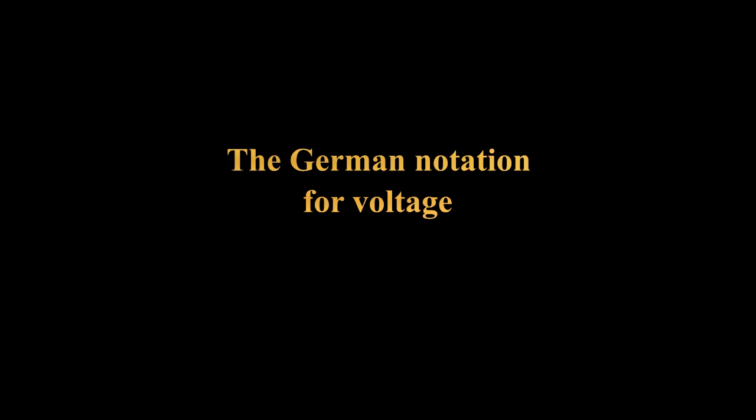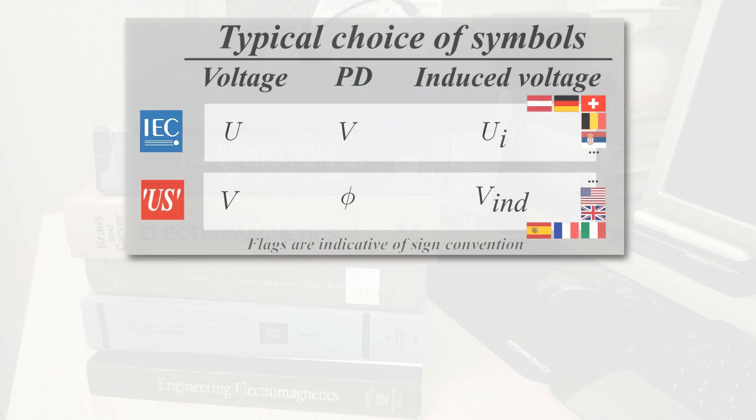Before delving into the IEC definitions of voltage, potential difference, and the likes, we need to clarify that the IEC uses the symbol U for voltage, whereas I use V, and the symbol V for scalar potential, where I use phi instead. Fun fact, the reason for using U for voltage is not to avoid confusion with the unit V for volt, but to avoid confusion with the letter V used to represent the electric potential.